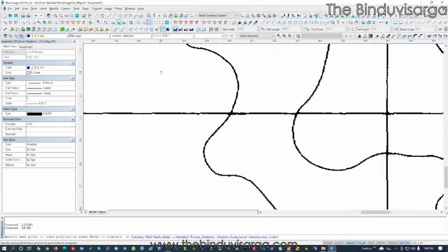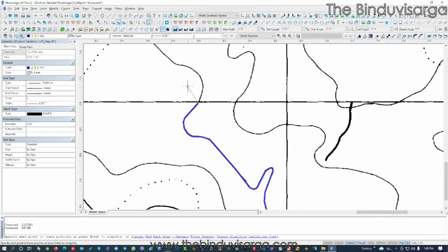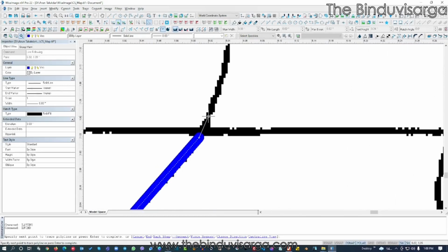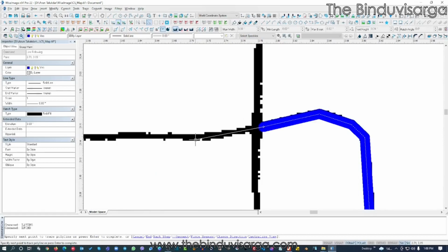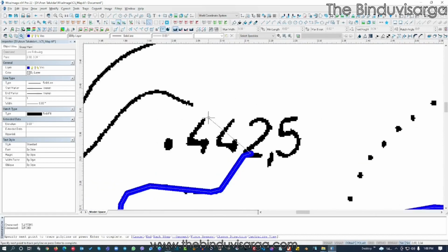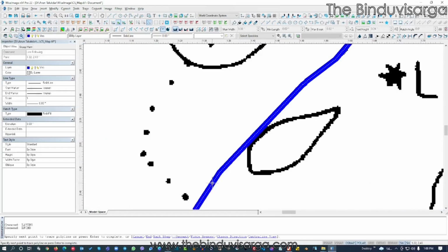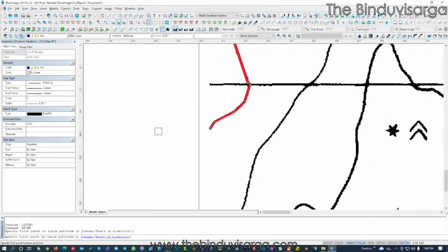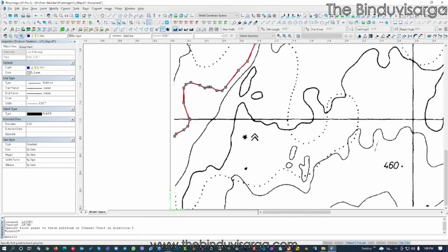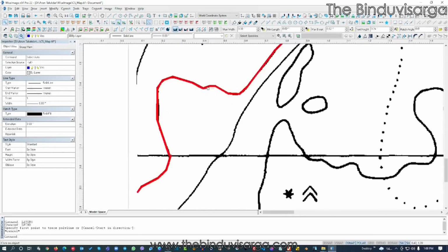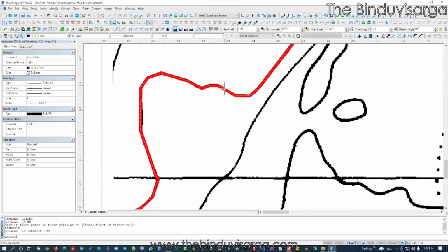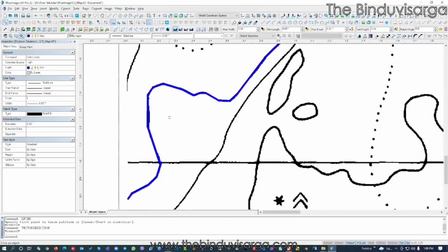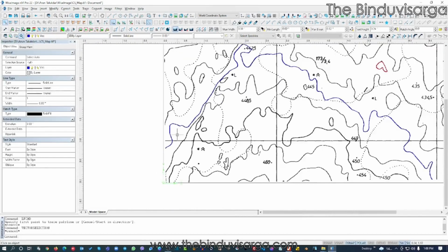You see, the moment I click, it actually drafts the whole contour until it meets some cross point. So now it asks where to go. I say this way, and now the text breaks things off. So I'll go this way, go this way, and that's it. So this is my contour now. I can select the contour like this, and this is the forced color. I should use the by-layer color. So now I have the entire contour ready for me.